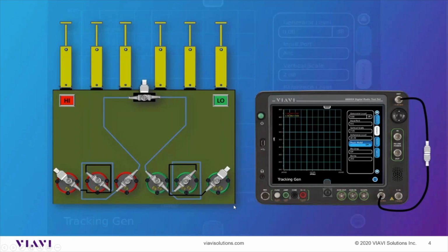Now, this particular one is a band reject or pass notch duplexer. It's got 6 individual cavities. You've got 3 cavity resonator groups in each of the duplex branches. So basically, I've got my high pass on our left side, and the low pass on the right side.